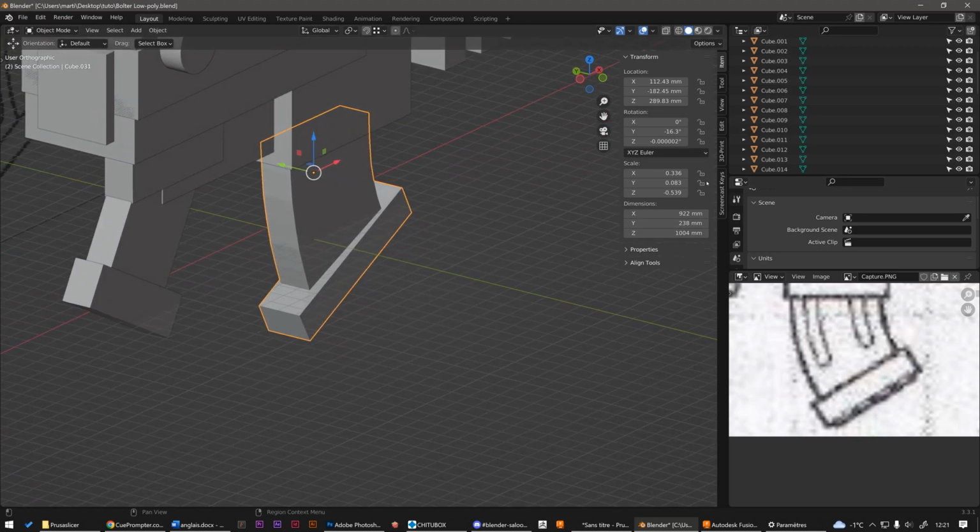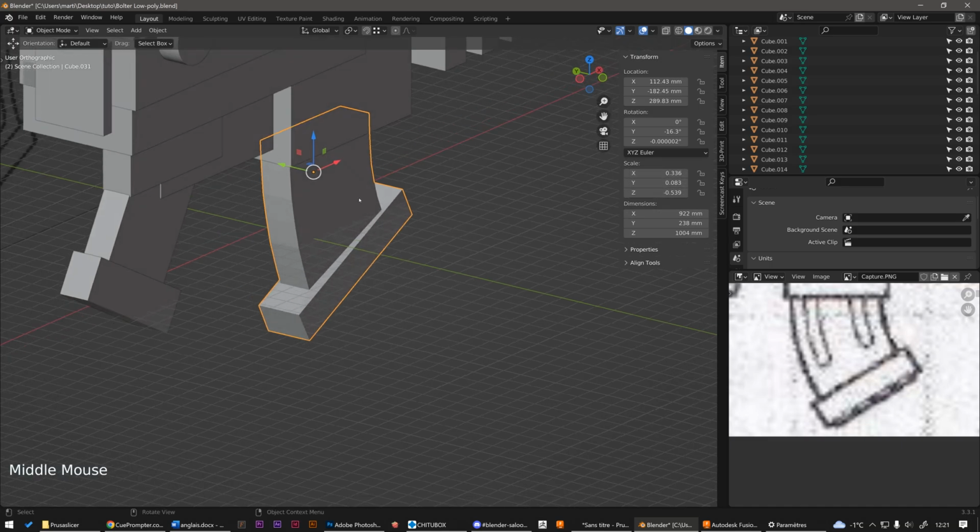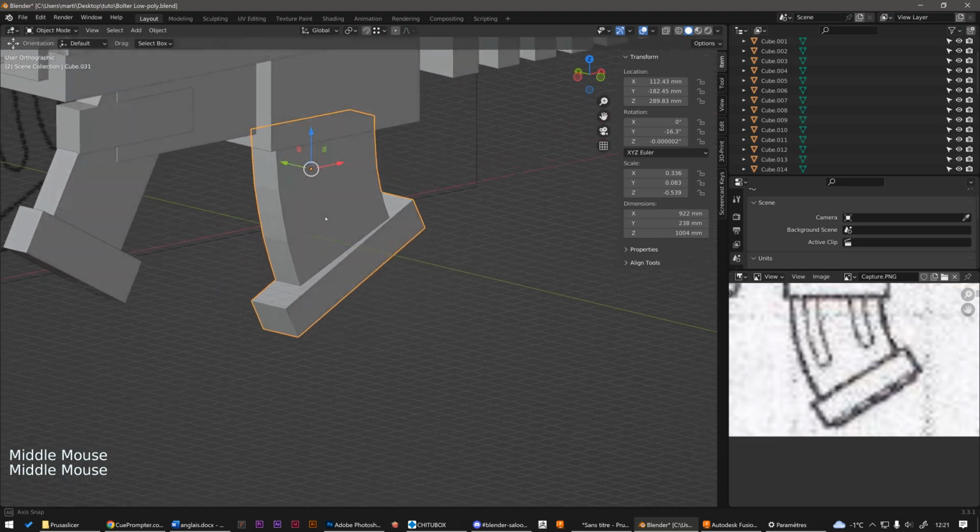If the object had been scaled uniformly, with 3 identical values here, we would not have had the difference, but there, this imbalance shows us that the volume of the object as it looks here is not its true volume. It is deformed by a scale that is bothering us. So we will have to reset this scale, i.e. make all these values equal, back to a uniform scale of 1, while keeping the object as it currently is, because its dimensions are like we want them to be. We don't want to change it.